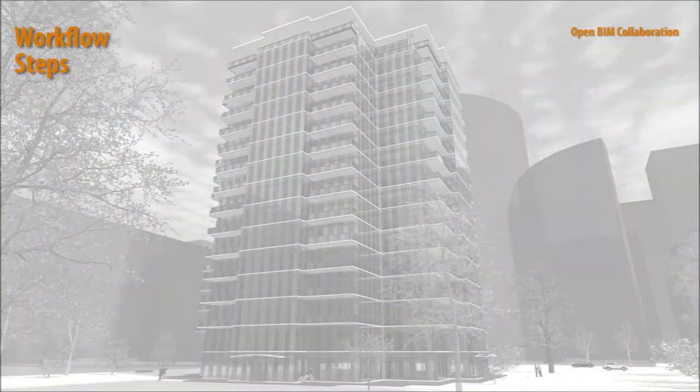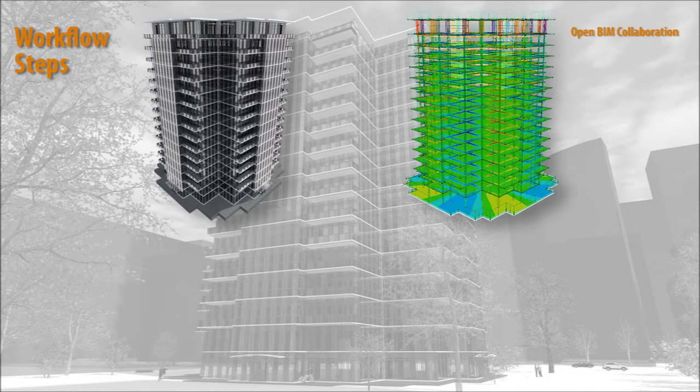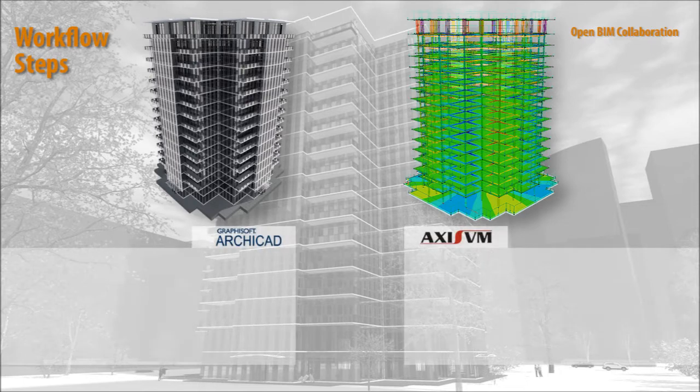First, an overview of the main steps of the Graphisoft ArchiCAD and AxisVM workflow. Let's start with the architectural model. Architects create an initial model version based upon the client's request and the given building site. Architects filter the structural elements by using element classifications, layers, layer combinations, display settings, selection modes, and so on to prepare the model for export.